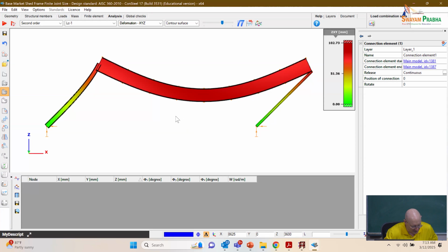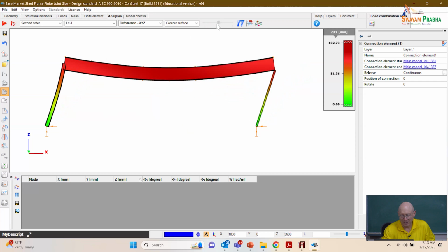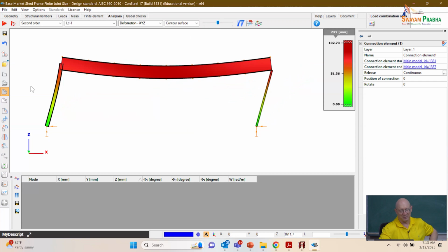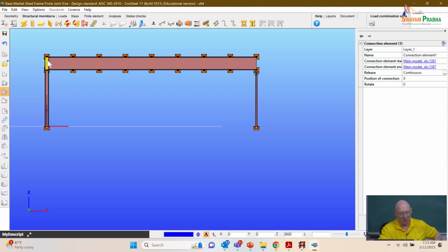All right. Now, another aspect here, and Consteel, if we went to its design capabilities, would handle things in this way once we've modeled that joint. So if I go back here, I'm modeling this panel zone with the joint wizard. And so in sizing the wide flange column, or checking it here on the left, it would basically say, well, that member stops at the bottom of the girder, right?